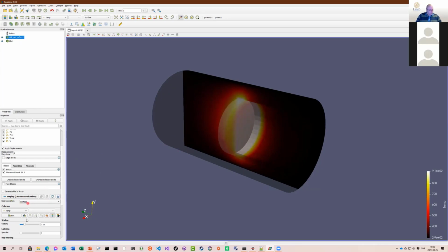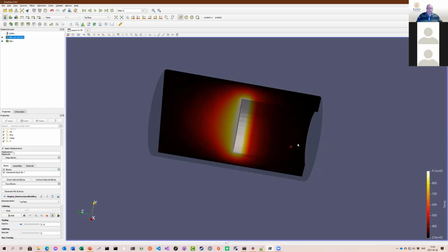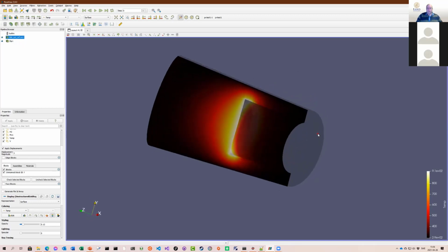What we can also do is make it very transparent like this. We keep that. But now we want to do flow lines here, so we will visualize the flow inside this model. So we press the model here. We want to make the flow on the time model, not only from the clip, but from the original model.